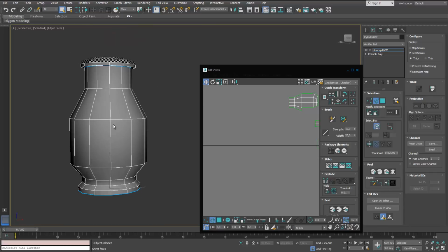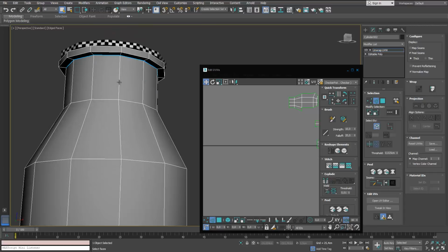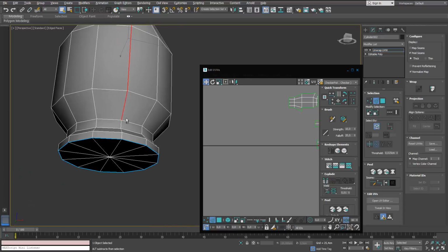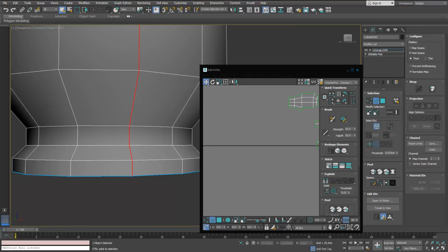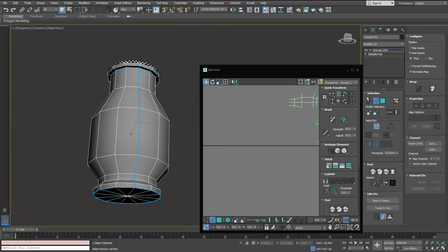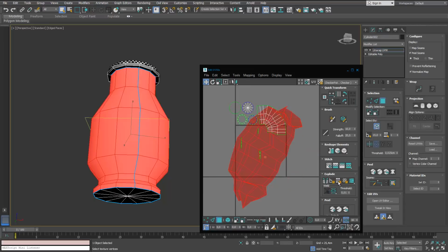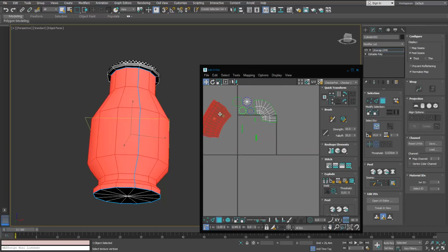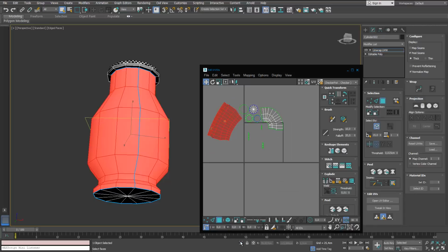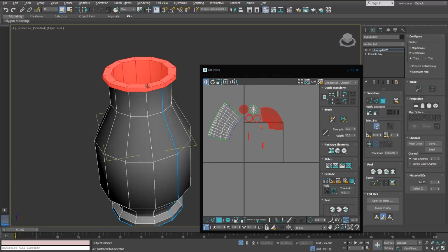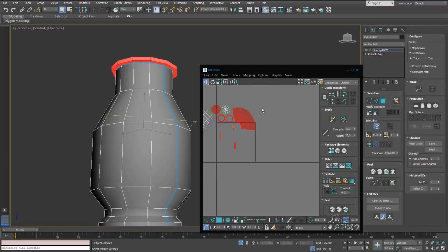All right, just select the edges and convert them to seams, and you're going to cut this surface open in order to use the pelt tool that is going to allow us to relax it. So start pelt, and we're going to use the pelt mode in order to make it relax even further. The same thing goes for the other sections.